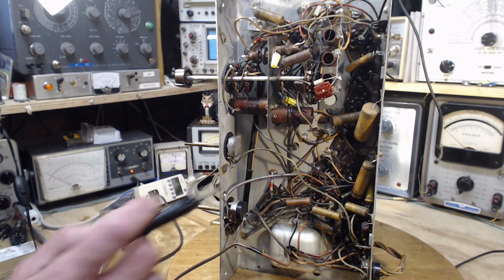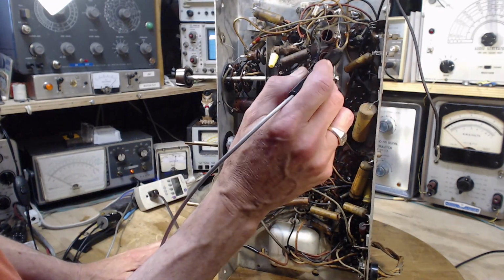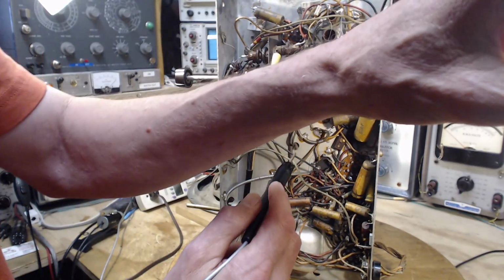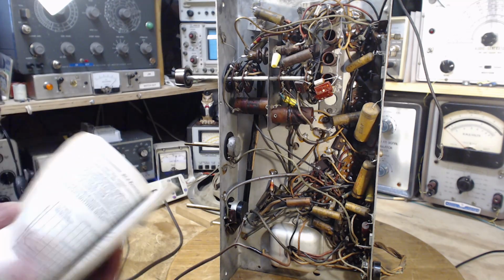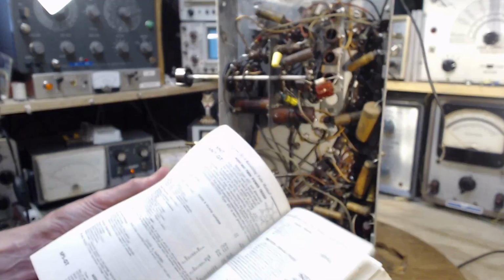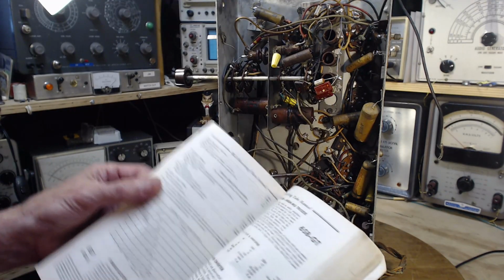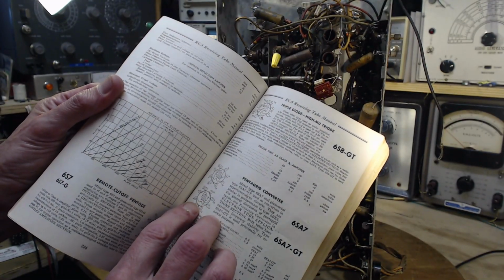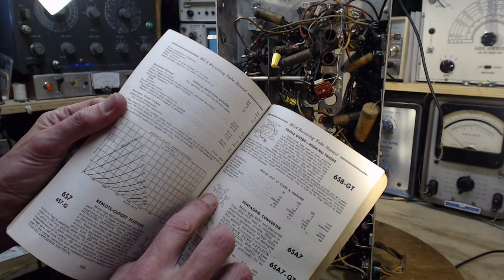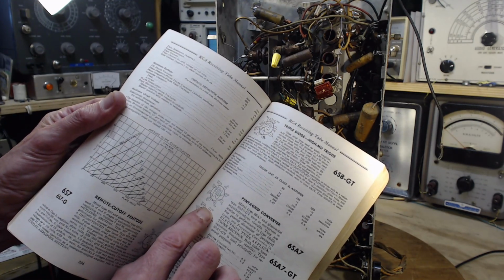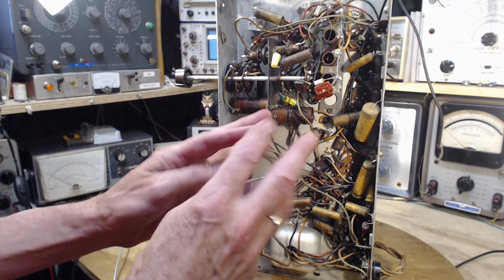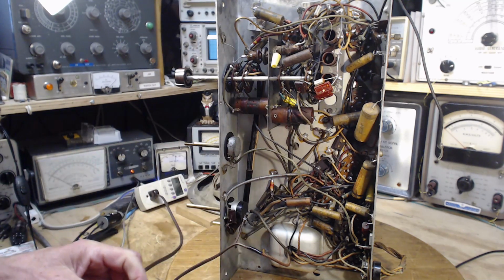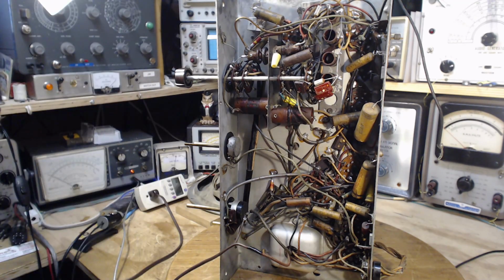So it's grid 3 on the mixer tube. Now the radio's not switched on, even though it's plugged in and the power's on. It's grid 1, and I don't know what pin it is offhand. So it's a 6SA7. And we'll find grid 1 is pin 5. Yes, grid 1. So there are two signal grids, if you like, grid 1 and grid 3, on this kind of tube. The antenna is hooked up to grid 3, and the local oscillator is hooked up to grid 1. The two of them are operating the tube together, and that's where the mixing goes on. And you get the sum and the difference of the two frequencies that are in there, mixing it up.